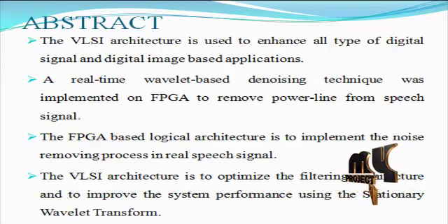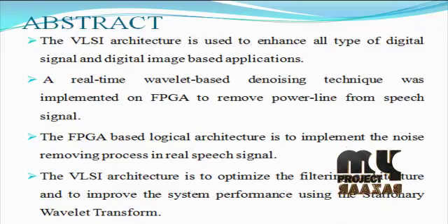The pre-processing step in modern digital hearing aids is denoising, to estimate the signal in the band of interest from the available noisy signal without altering it. Advances in digital signal processing have allowed adding features to improve the performance of assistive listening devices, like speech enhancement and noise reduction. Furthermore, progress in field programmable gate array technology, especially for miniaturized system applications, has facilitated the implementation of small, portable and high performance devices.